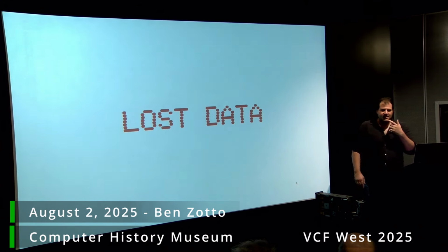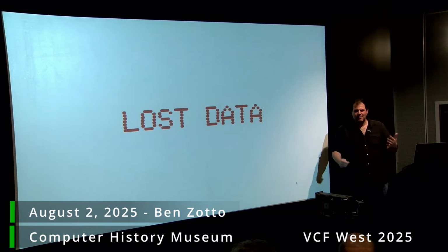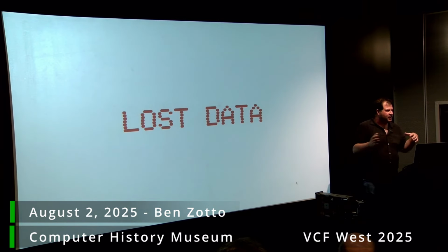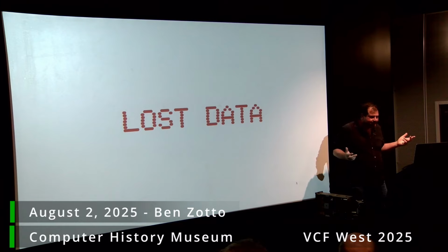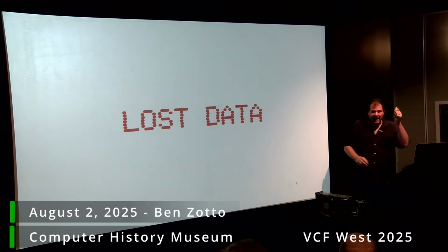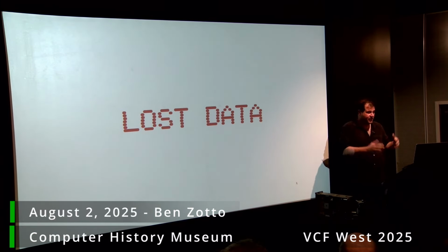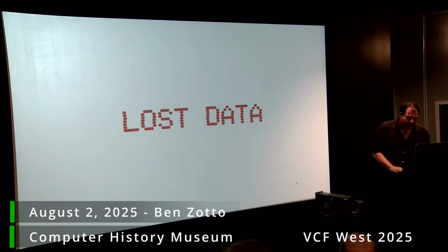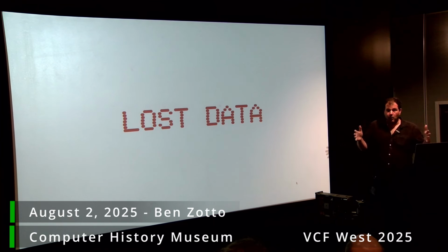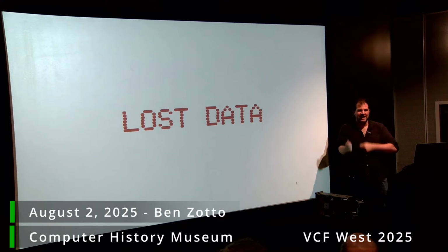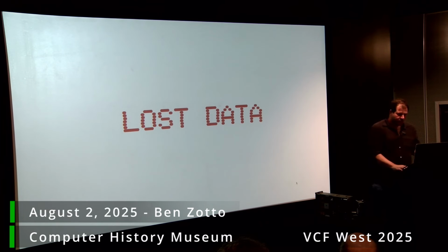But then I realized it didn't work. I thought it worked, but it turns out only 250 bytes out of my 256 byte sectors were actually showing up. And there's a special flag that the 1771 controller sends you called lost data. So I was like, oh, lost data, crumbs. Maybe it's a scrappy little chip. It doesn't buffer the whole sector. So unlike those controllers, you have to pull the data out of it one byte at a time. And you have to do it in a timely fashion, else. So maybe I'm not able to keep up with it. Let me figure out if I am.